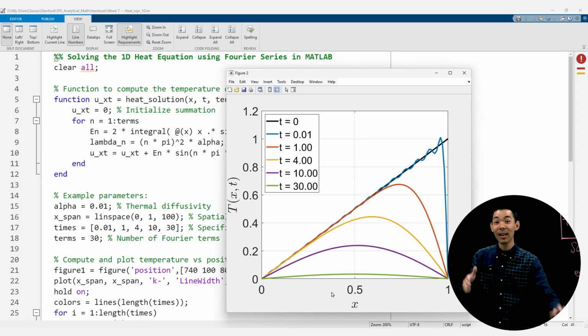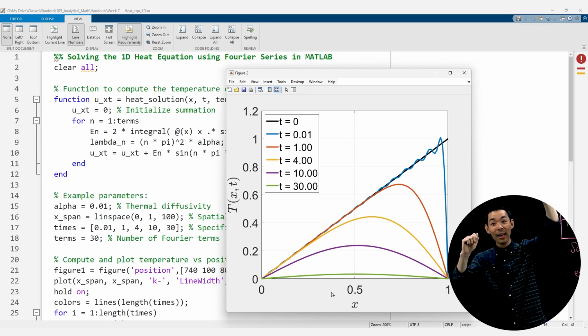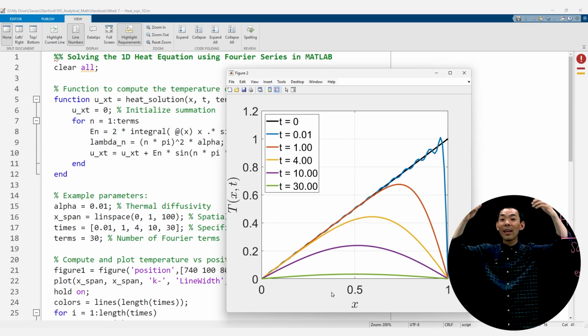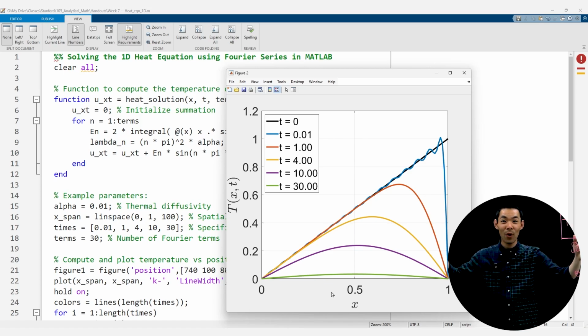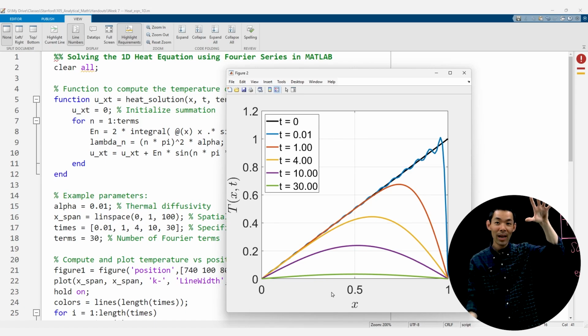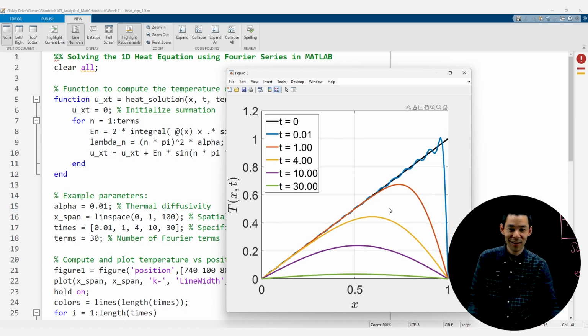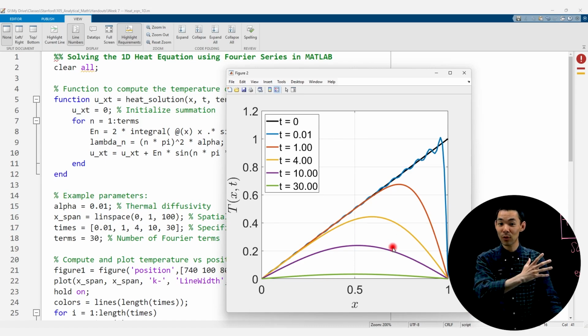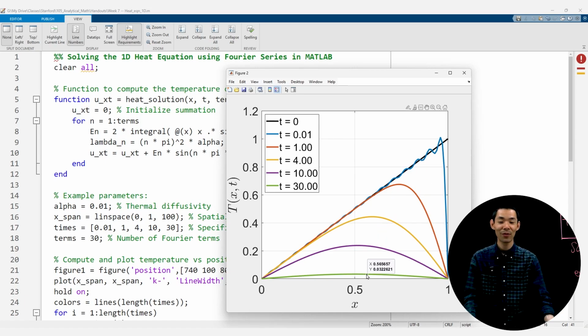And you're seeing that heat is initially very high along the right-hand side, that's the warmest, and that heat gets dissipated into the infinite bath, the reservoir of ice bath set at 0 temperature on both ends. And the right-hand lobe down here is decaying more slowly, of course, because the right-hand side has more heat and energy stored there initially, and it gets lower and lower and lower as a function of time. So that's why it's kind of an asymmetric profile on the right-hand side that decays as a function of time.